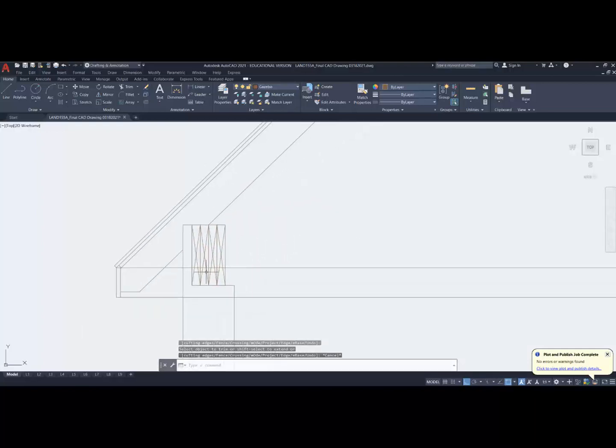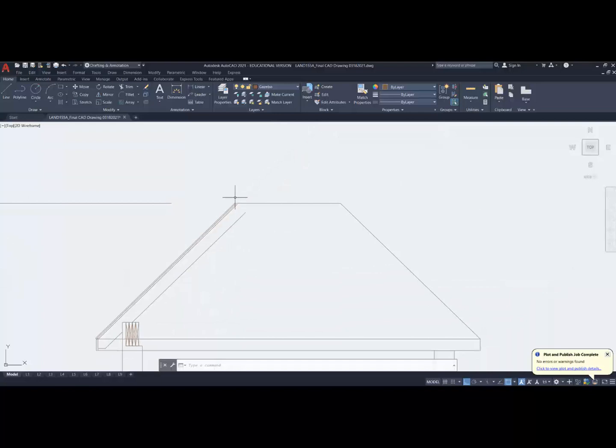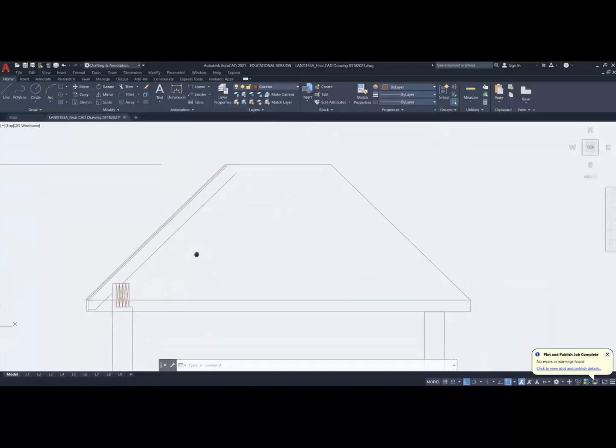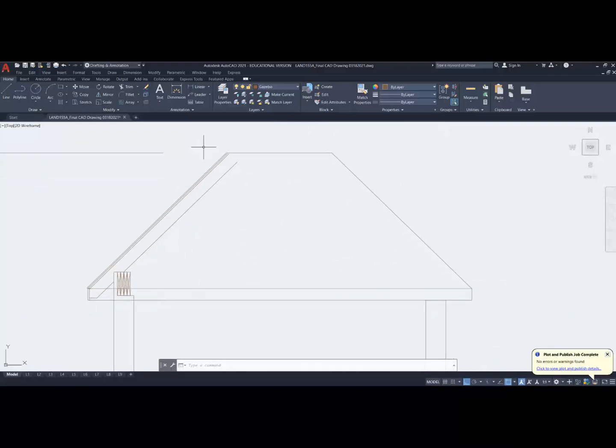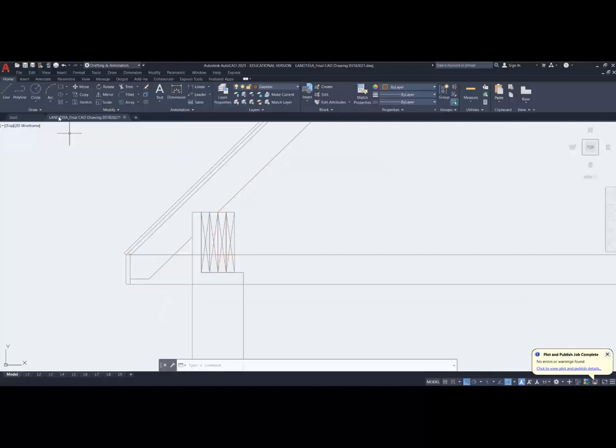See, we also have the fascia board in the front. We also see it from behind, and we're going to get to that detail a bit later on. Okay, so here are some of the elements, and I can mirror this over, but we're just drawing a section. I only need to see part of this. This is the only part that I need to see. I will need to see the joists coming down in the other direction, and they're coming down on 16-inch centers. So let's make that decision here.